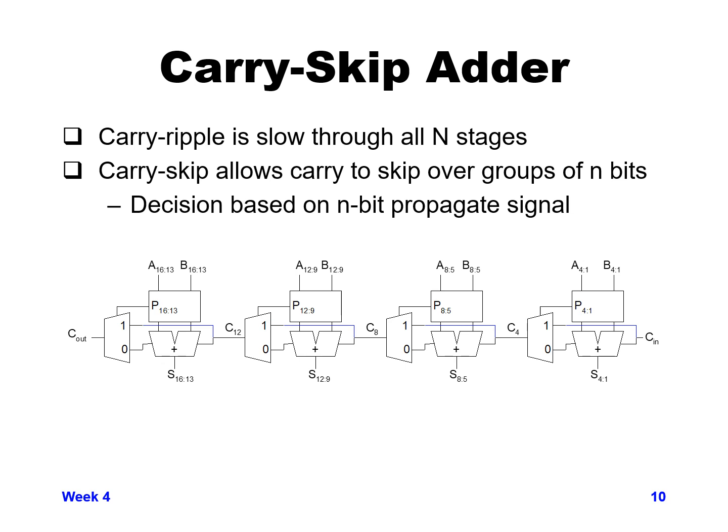In effect, you can lump bits in groups instead of having each bit be its own and carrying through each bit. The example below is: let's say we have 16 bits and we're lumping them in groups of 4. So we can take groups of 4 and calculate, based on just that group of 4, what our propagate value would be.